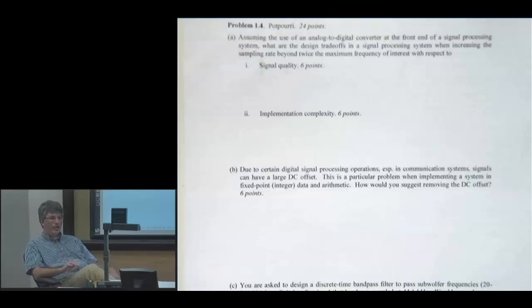The sampling theorem is an excellent place to start, but we don't stop there. It just tells us that the sampling rate has to be more than twice the maximum frequency that we care about. What did you do in homework 0 and 1 when you were plotting signals and finding spectrum? Oversampled like crazy. Like how much? I might do 1,000 to 1. Why not? It's in MATLAB, the bandwidth was low. And in practice, we do 1,000 to 1 in data converters, which we'll talk about in lecture 10. 512 to 1, 256 to 1 for audio converters. It's coming up. So oversampling is a good thing.